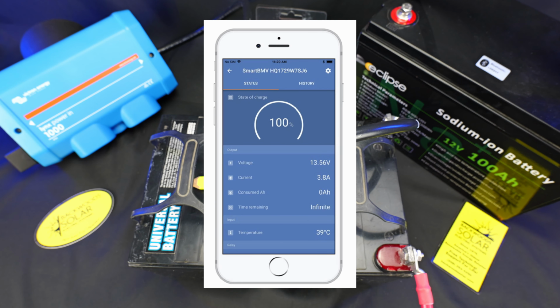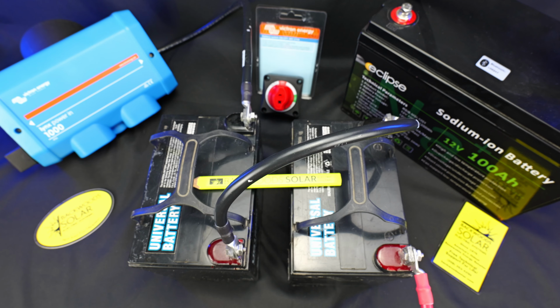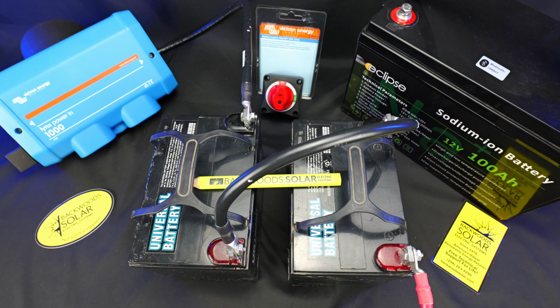Using a battery meter like the BMV712 just gives us an easy at-a-glance gas gauge, regardless of battery type, to get a good understanding of our capacity. Instead of having to use voltage or some kind of voltage table to cross-reference voltage and capacity, the battery meters just give us a clean, understandable data point.